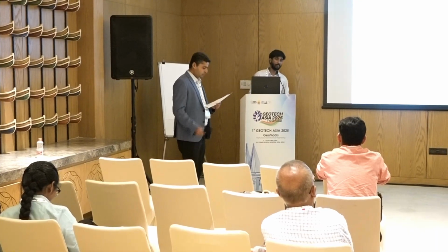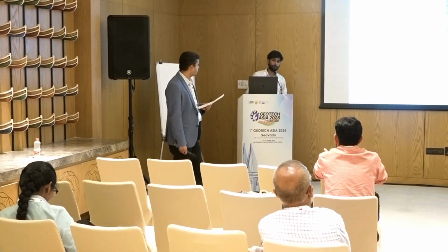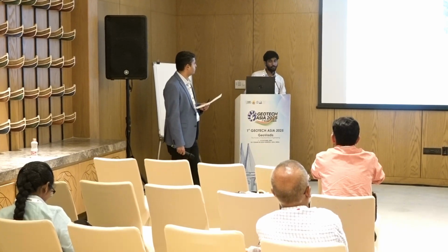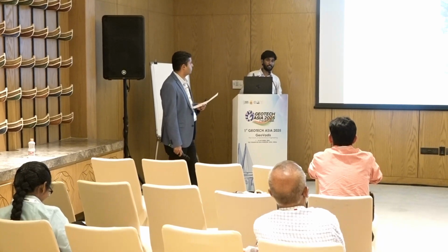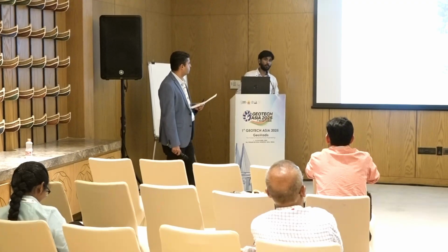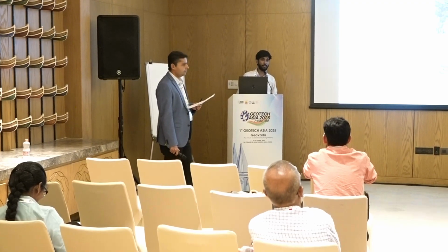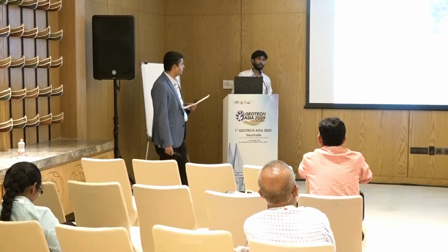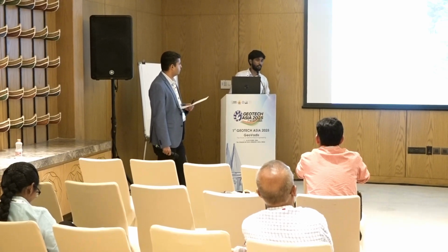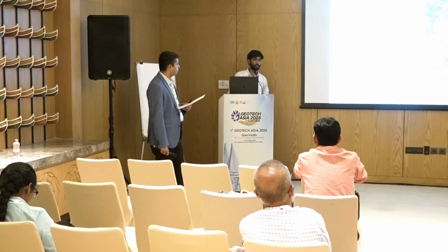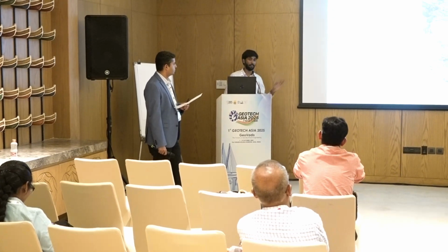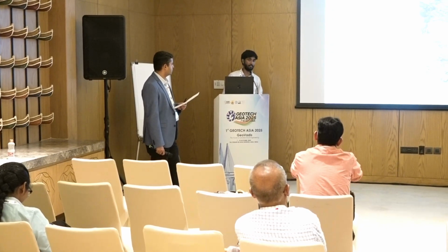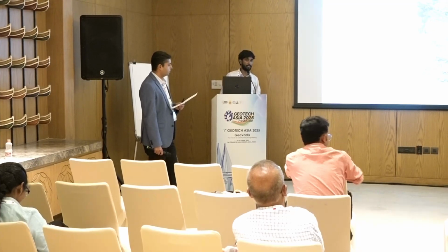We have already tried the falling head, but it's not working. It is not giving water coming out of it. It's so impermeable that we waited for almost 6 months, but have not seen even a single drop coming out of it. That's why I have calculated with MV and CV values, a correlated equation.